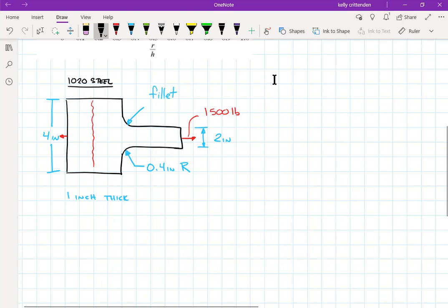It needs to know what material it is, because it's going to solve not just the stress, but also the deflection, you know, how much does it stretch and all this kind of stuff. So it needs to know what material. So for us on this side, on the stress concentration side, it does matter because the stress we calculate needs to be compared to some material properties to see if it's too much stress, but the calculation doesn't care what material is there on this side.